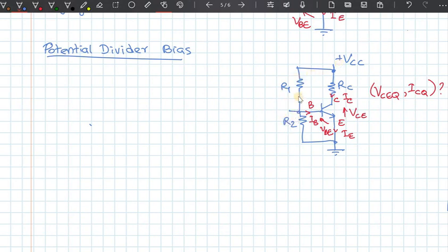But the problem in that case is that this is just there to maintain the voltage at the base, and that current passes through R1 and R2, and I squared R losses will be there, which is not contributing to our signal. So therefore we do not want R1 and R2 to be really small most of the time, so as to reduce the fixed power dissipation across these two.